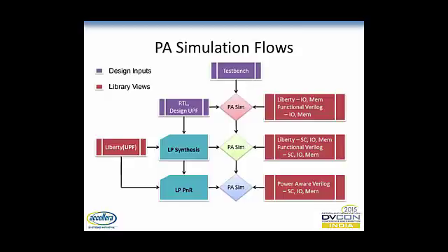This is an overview of at what stages generally we can execute the power-aware simulations and what are the different views or physical IP views which get consumed. Any normal simulation starts with an RTL and a test bench. But in a low power flow, you have to specify the power intent in Design UPF along with RTL and provide it to the simulator.